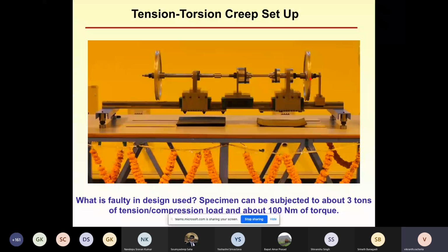So using this setup, we had thought we will apply tension torsion, and we had designed the columns, the ball screw, everything in a manner that nothing will undergo plastic yielding, even if you apply 3-ton force on the specimen, meaning about 30 kilonewtons, and about 100 newton meters of torque.